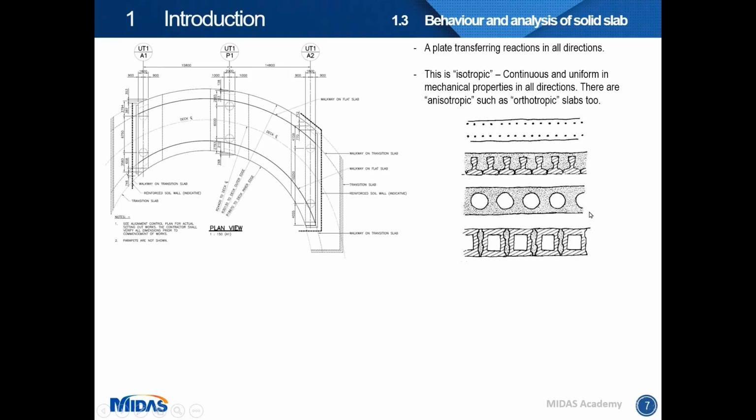The last two diagrams here show two types of voided slab. They are voided compared to a solid slab. When these voids are less than about 50% of the overall dimensions, the effects of the voids would be considered insignificant in affecting the deck behavior as a plate. Otherwise, the extreme case would be like a multicellular deck, a box girder or multi-cell box girder, something like that.